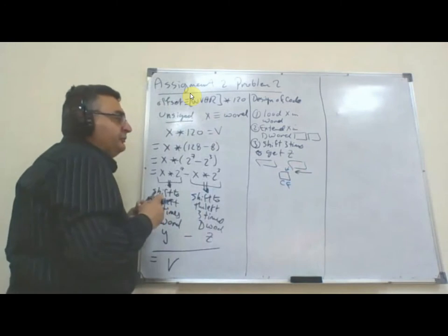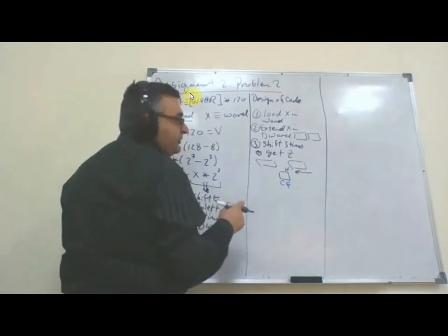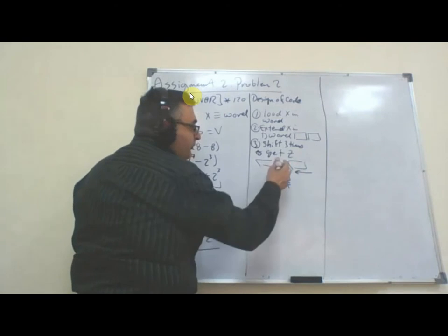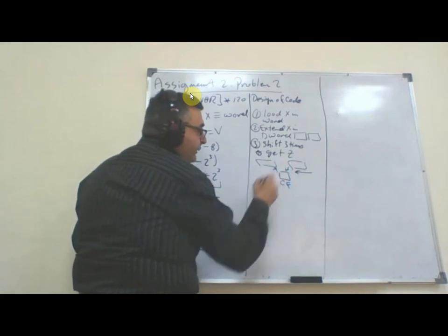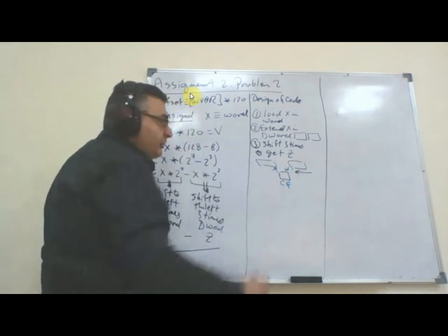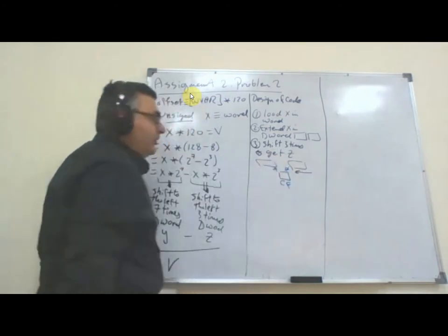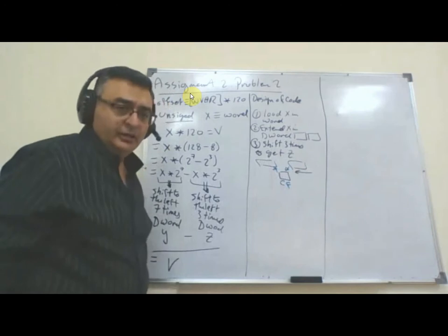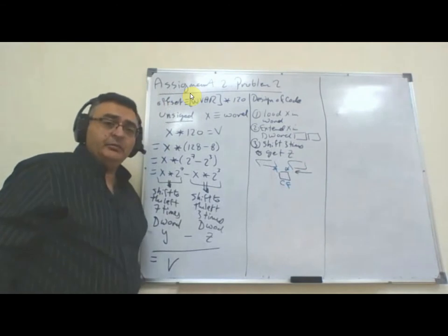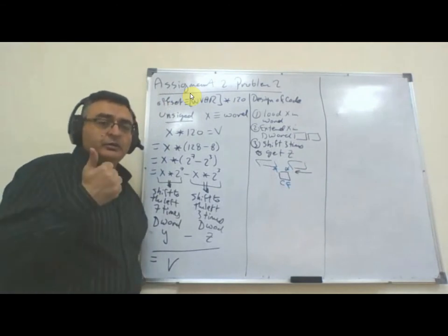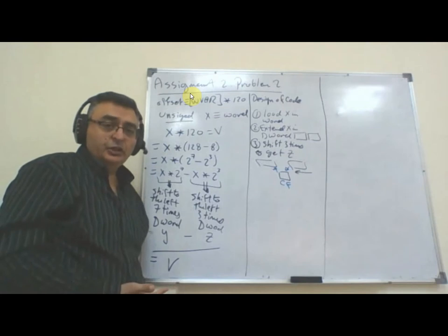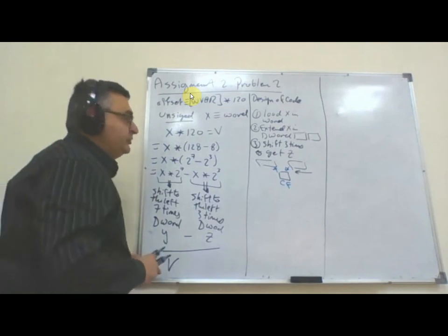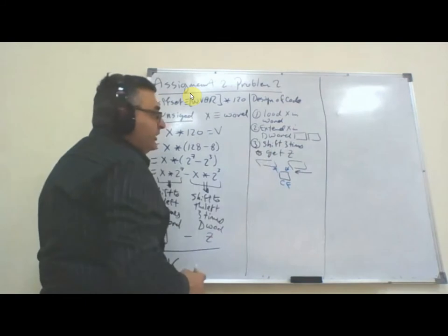Then shift the shifted-out bit from the carry flag into the other register. So using this mechanism, I shift out the bit from here and shift it inside the number here. This can be done either through shifting with carry or rotating through carry, or add with carry. Both will do the same. So I will repeat this three times.